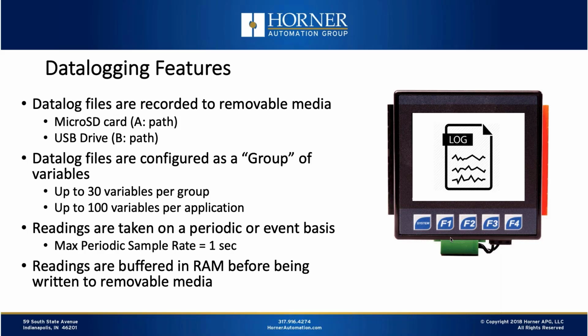When you do data logging, you effectively assign a group of variables that you're going to log to a spreadsheet, let's call it. You can have up to 30 variables as columns across any one spreadsheet, and then you can have up to 100 variables for your total application. So you might have one group of 7 variables and another group of 35 variables, et cetera. 30 variables is the maximum for one group.